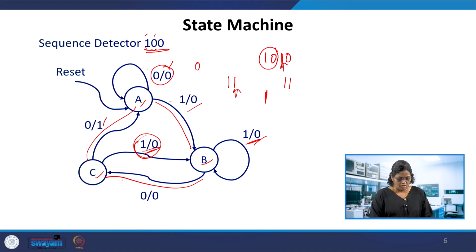One more thing we can notice in this part is the reset. If you have a separate reset in the Verilog module, it can help stop the state machine anywhere, and you can have more control over it.